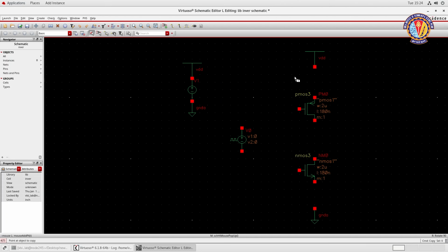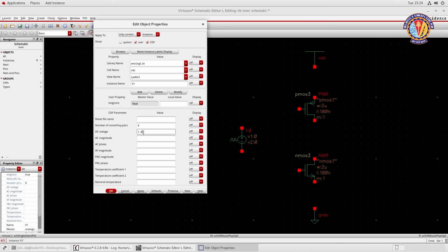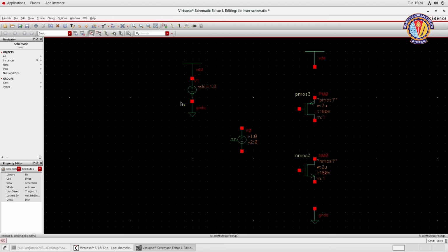Right? Here you can see this VDD now is a standalone symbol. It's just a symbol which gets the value from this voltage source, which is a DC power supply. Again, we need to change the properties. We'll go to properties. This value is 1.8 volt. Fine. Now we can realize that this VDD gets 1.8 volt because of the circuit which we have created here. Okay. So irrespective of your circuits from here on, be it sequential or combinational, you will have a VDD. So once you have this VDD placed, you need to give such a configuration, or else your VDD won't have any value and the circuits won't run.